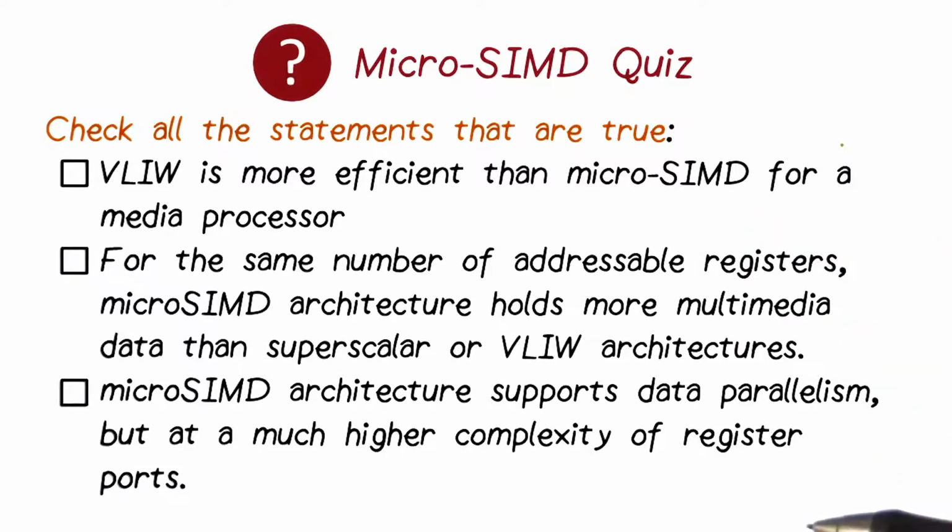VLIW is more efficient than micro-SIMD for a media processor. Is that true or false? It is false. Since micro-SIMD can pack a lot more data, it allows not only a higher amount of parallelism, but it also allows a much more compact data segment.